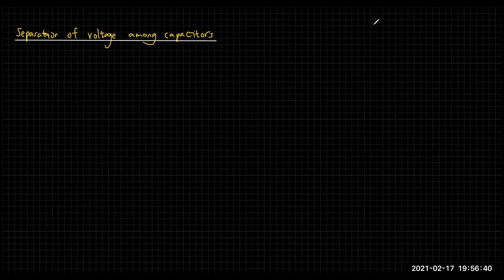Now, if you consider a circuit with resistors from your O levels, that is not that hard. Let's say there are two resistors like this. This we will be learning in A level as well, in the next unit. Imagine this is 10 volt, this is 2 ohm, this is 3 ohm. Current is going to flow through the system. Since they are in series, the same current will flow through both resistors. My question is, what is the voltage across each of these resistors?